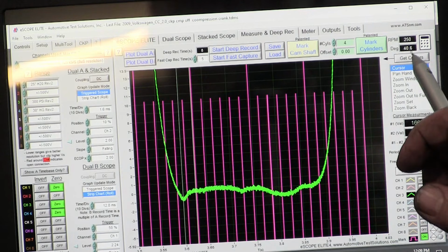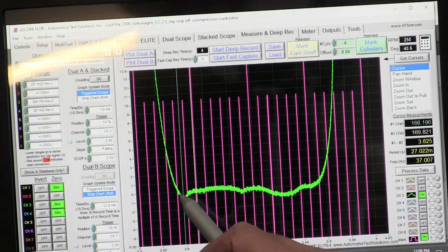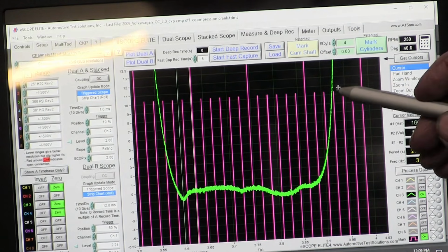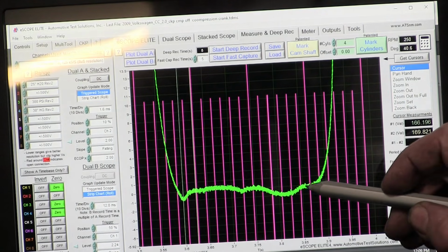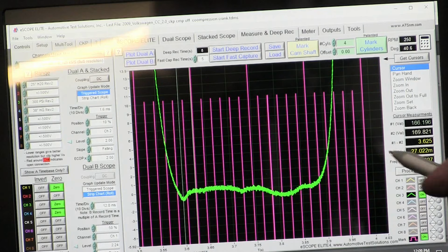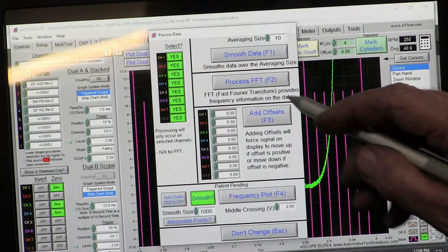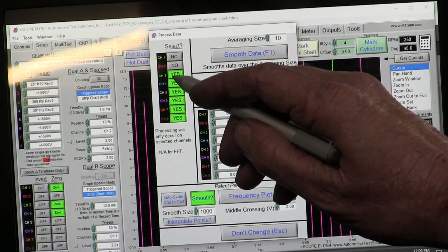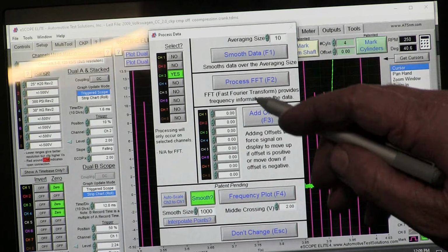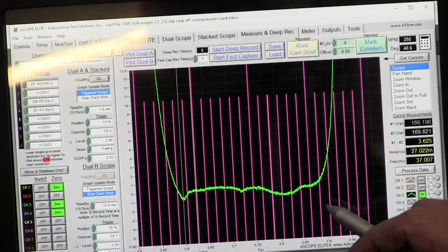So we're at 40 degrees before bottom dead center. That tells me that that exhaust cam is operating correctly. But do you see where the intake comes all the way down? It doesn't come flat. It rolls all the way down. So one thing we can do is process this waveform, and that's just going to clean up a pressure waveform. We don't process cam and crank, but we want to do this.